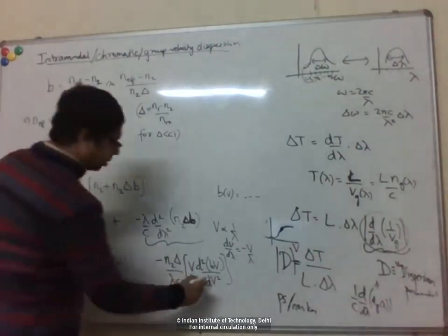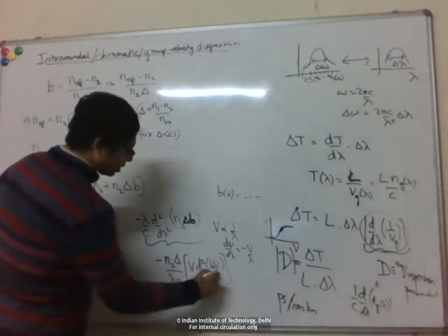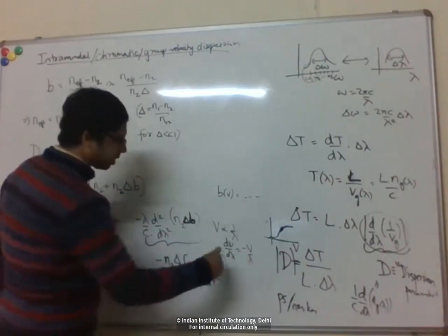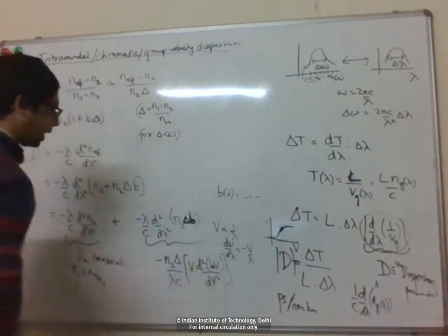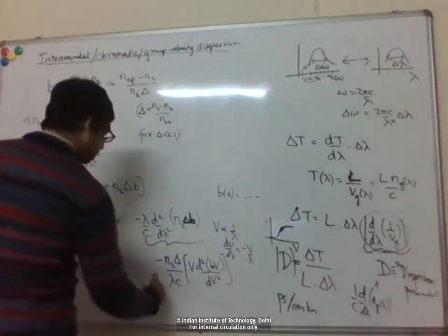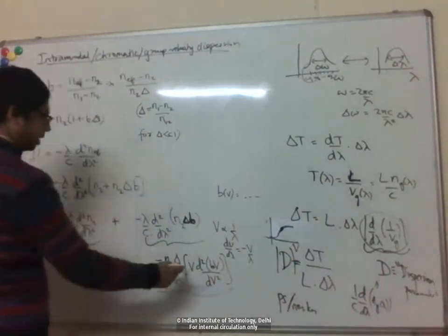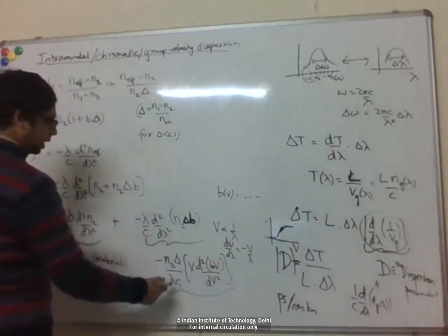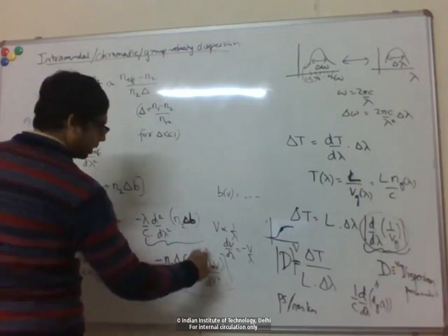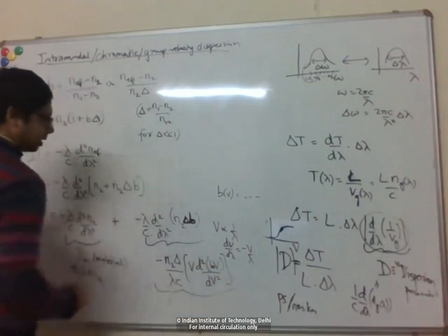Right, so you can see here basically now it depends on the, so B is a function of V, right? So you see that somewhere this depends on the slope of this BV curve, I mean, the second derivative. So this is the waveguide contribution, right? So even for constant N2 and delta, not a function of wavelength, just from the BV curve, this will be a non-zero number, right?